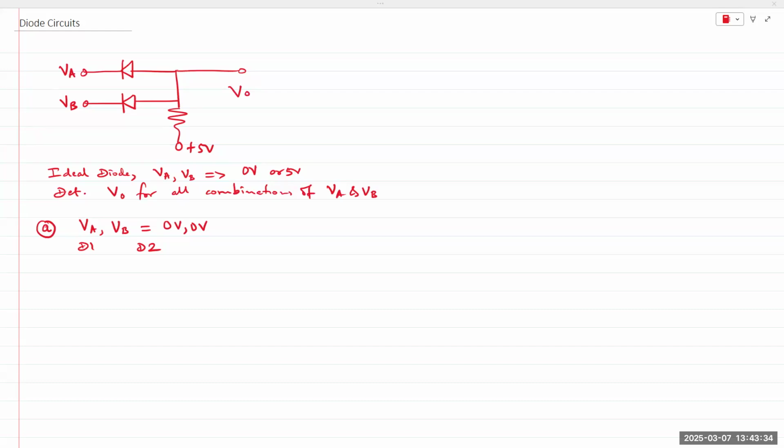If we find the Thevenin equivalent circuit as seen by the diode, what do we see? One voltage source, one resistor. So the Thevenin voltage applied to those diodes is plus 5 volts, and the Thevenin resistance is resistor R, 1K. So the anodes are always held at plus 5 volts. Always. That's how we would begin analyzing the circuit. The anodes are permanently connected to plus 5 volts.